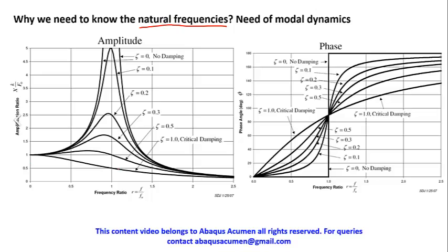Now this is where the loading frequency and natural frequency match. This is exactly equal to 1. This is exactly a resonant condition. So if you have an undamped system, then it will have infinite displacement, and once you add damping, then this displacement reduces quite a lot. If you have some external viscous damping there, then you can control this, but structural damping is just about 5%. So if the natural frequency matches with the loading frequency, it will have a very high deformation.